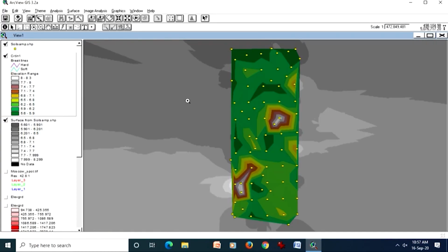So now the issue about the boundary. The TIN will not make a rectangular or square shaped boundary as in the case of raster, and therefore you are having boundary problems. I can make a subset of my raster very easily, but I cannot make a subset of my TIN.